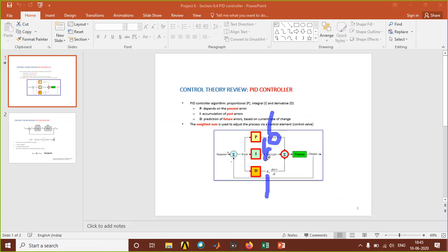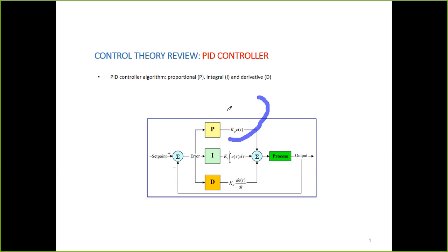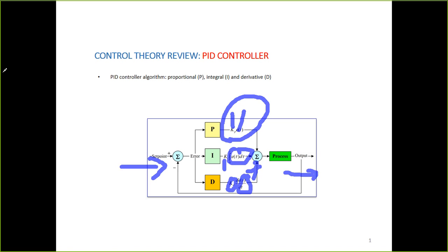There is nothing we should do here. But here I am supposed to integrate my error. So first, in this case, I'm simply going to use gain because it is error into gain. Next one is gain of Ki. It's a constant. I'm going to integrate my error for the time of 0 to t. Next, I'm going to multiply my gain with my derivative. Finally, I'm going to add everything. Input is error, output is process. So let us try.